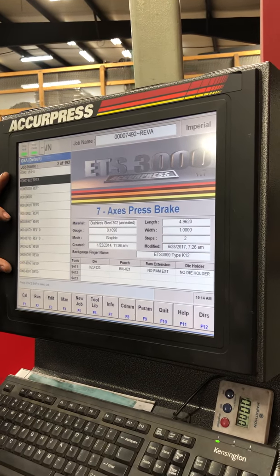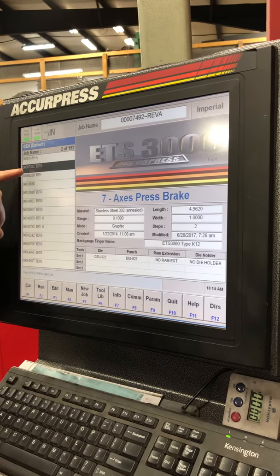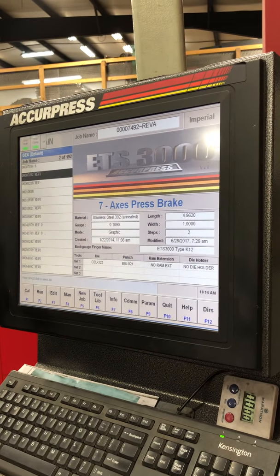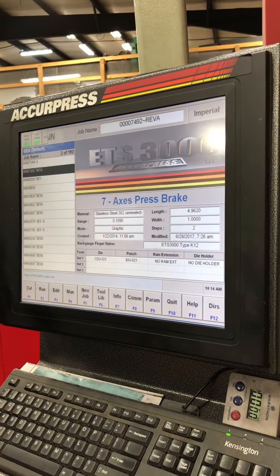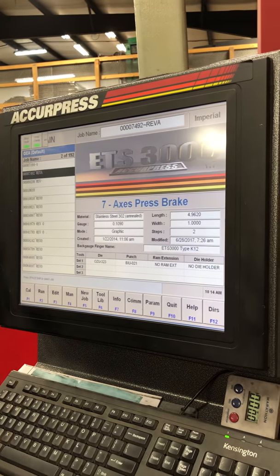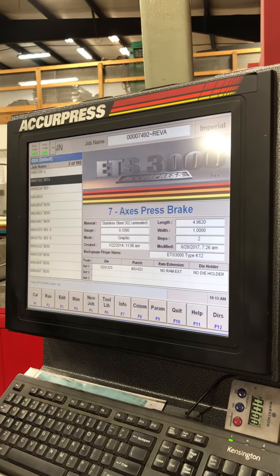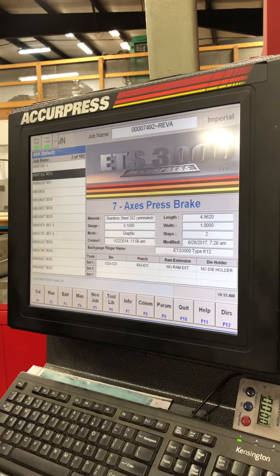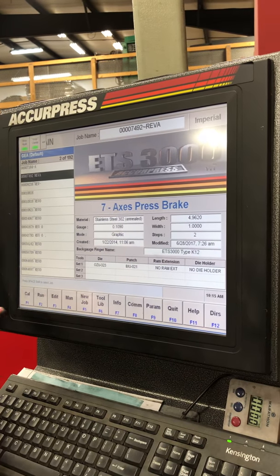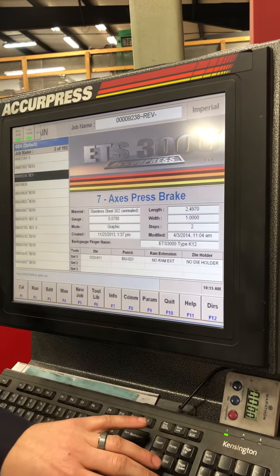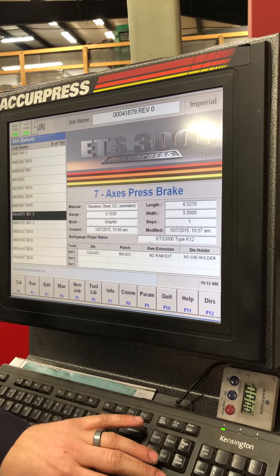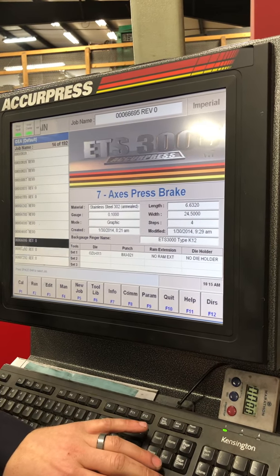So every part has the part number and the rev. They're going to match the part number, the rev, make sure it matches the drawing. If there's any rev changes, they're going to stop. They're going to see what changed. Does it affect them? Sometimes it's just a hole that changed, so it doesn't affect the forming. So they're just going to carry on with their job. But yeah, graphic, we got different ones where you'll see graphics, and then they'll go 3D programs.